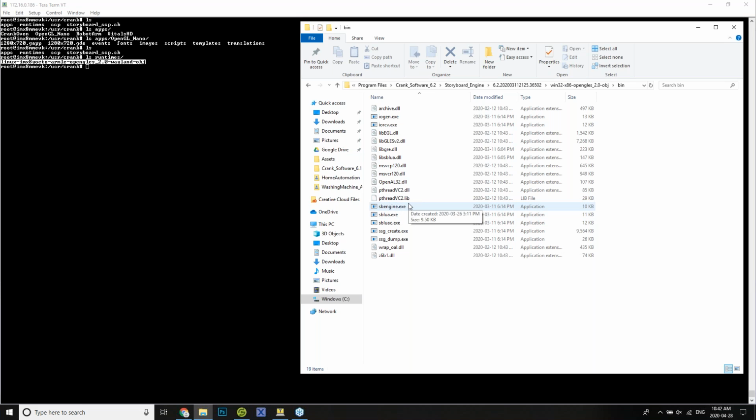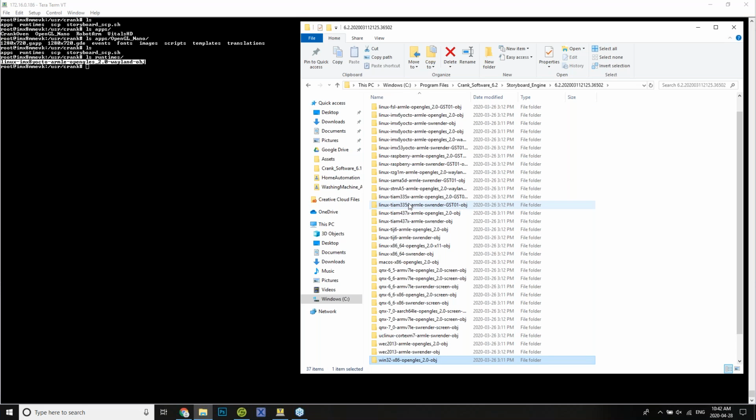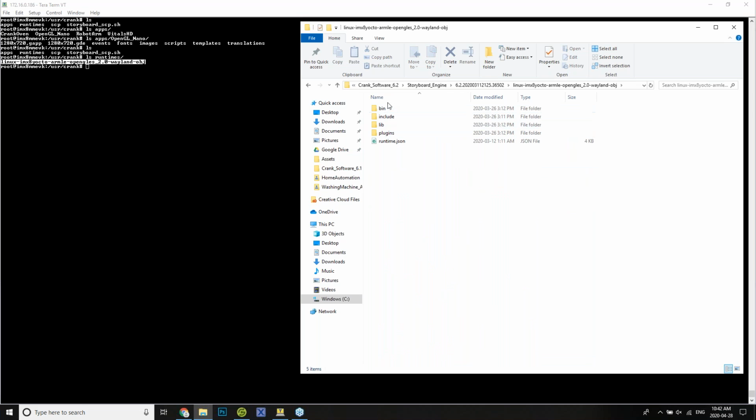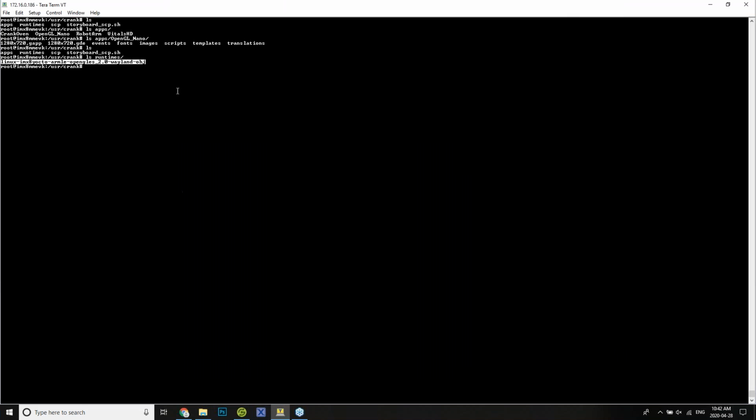So all of these directory structures are the same. So if I were to go back and look at the IMX8 one, they all contain the same structure. So all you need to do is drop that runtime on here. And in our case, the demo image is already configured. And then from there, you can write a script to launch it. In our case, we've provided one that you can use to launch an app if you want to deploy it over network and SCP.